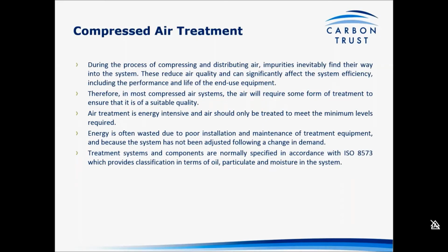So once you've compressed that air, you're then going to look to be treating it. By the very nature of sucking in external air and compressing it, there are going to be impurities in that, not least the oil that the air is going to pick up in the compressor itself. So I think in the vast majority of compressed air systems you would have to have some form of treatment.